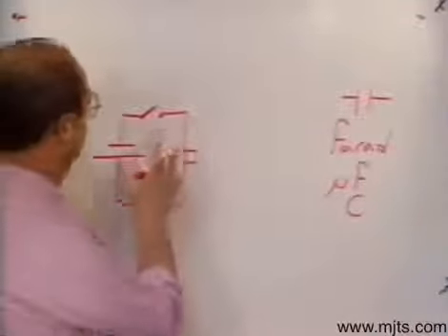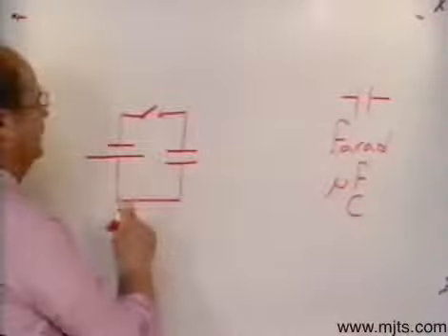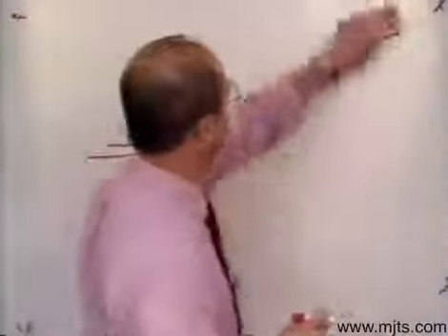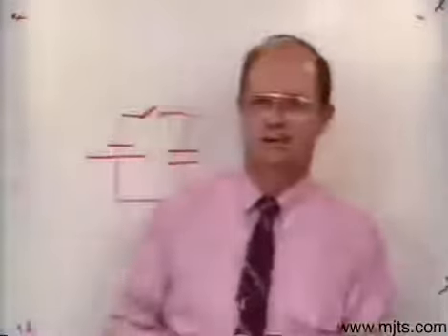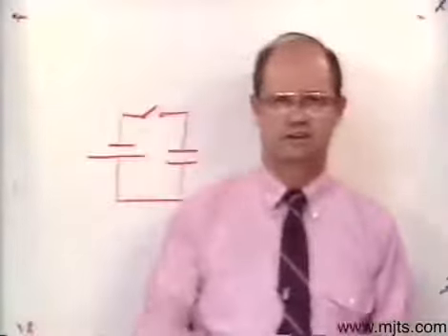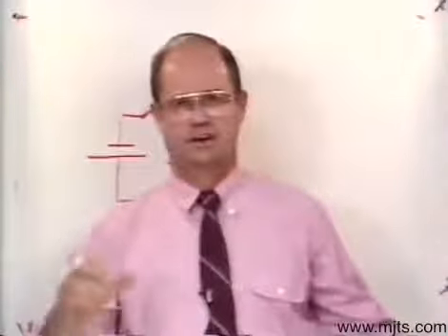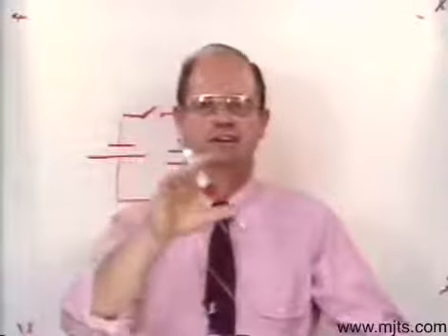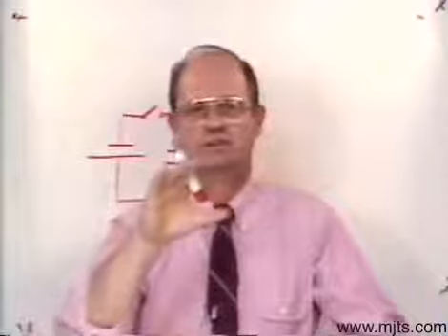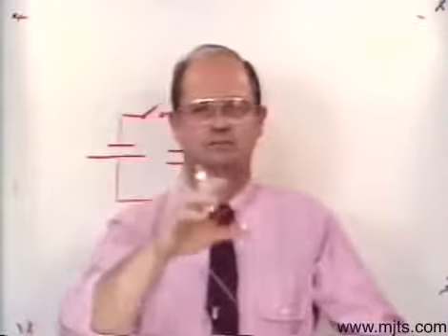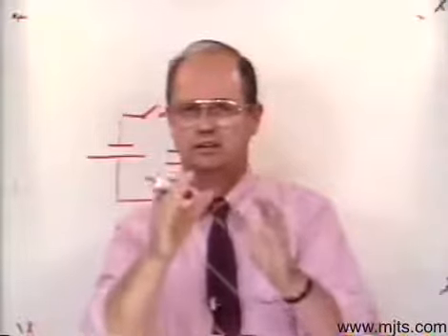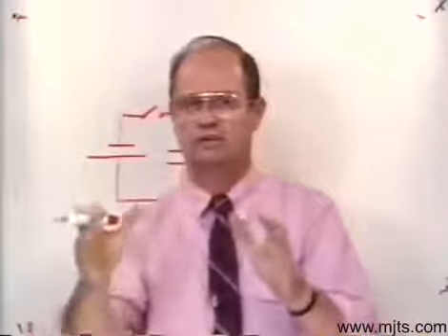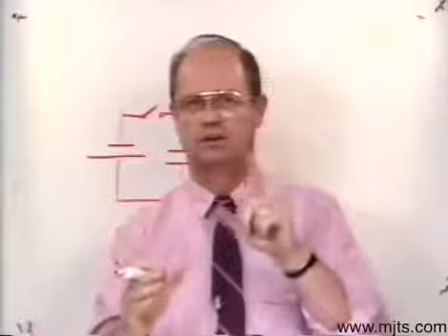Now, the effect that I would get from that capacitor in the circuit is going to be just the opposite of the effect that I get with the inductance in that circuit. We said if we had an inductor in the circuit, it would oppose a change in the current flow. 1 amp per second would give me 1 volt counter electromotive force. That would be at 1 Henry.